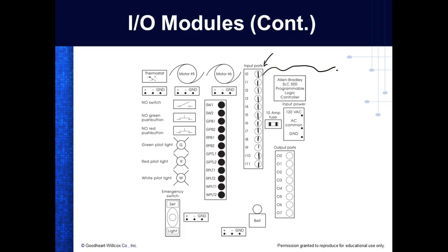And then my push button might be right here, or whatever I'm using. Now it depends on what this thing is looking for. So right now I'll just connect this up to plus 24 volts. So now if it's pressed, then I would get 24 volts in to that input. If I let it go, I get 0.